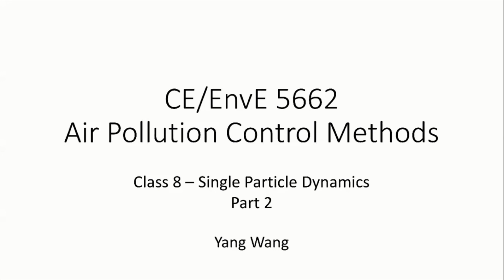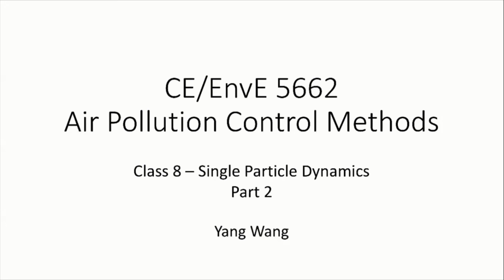All right. So this class, we're gonna continue our discussion on the single particle dynamics. The reason why we're very interested in these single particles, like drag force or all different types of other forces, is that people use these forces to remove particles. For example, in a coal-fired power plant, let's say it generates a lot of fly ash, then people might design a very long duct, right? If you have a long distance of duct, then those larger particles can settle down by gravity. So in this way, you can remove some particles.